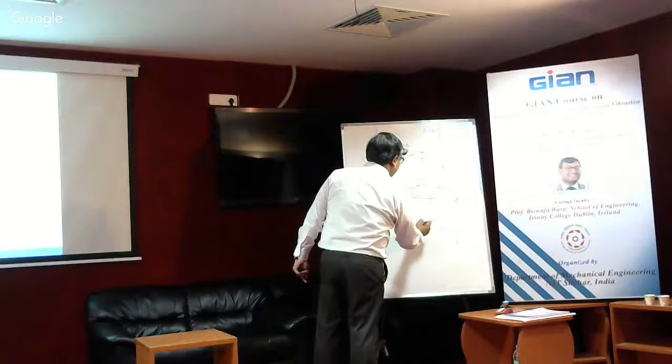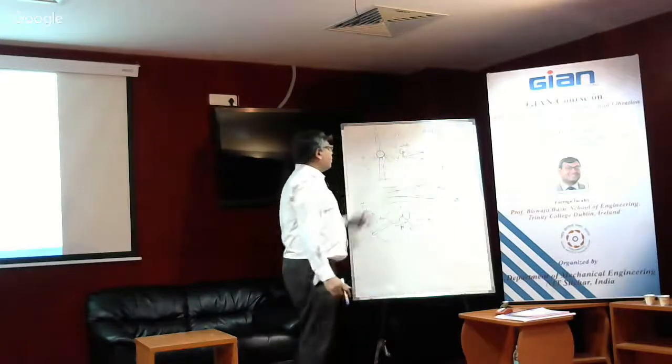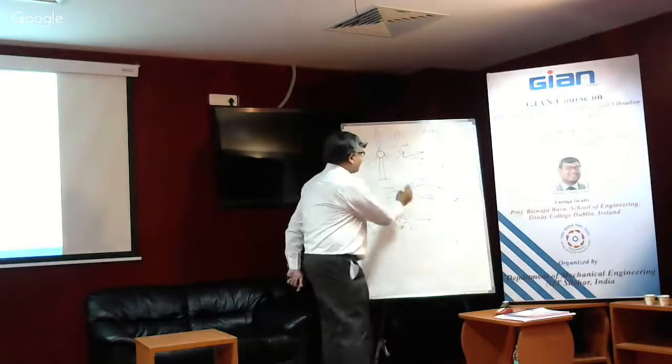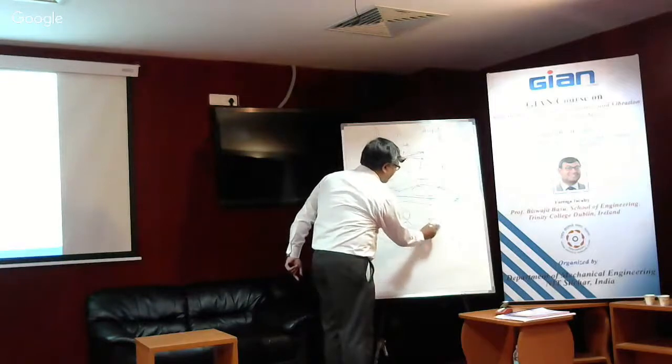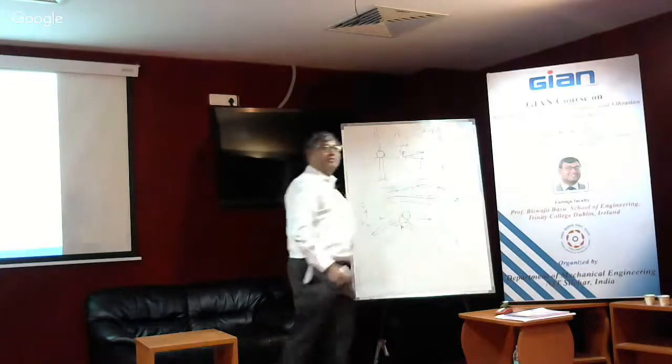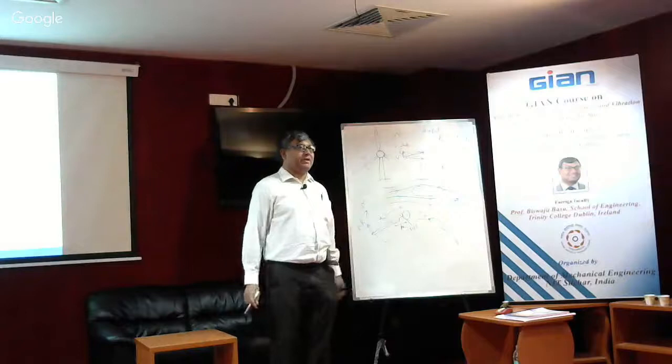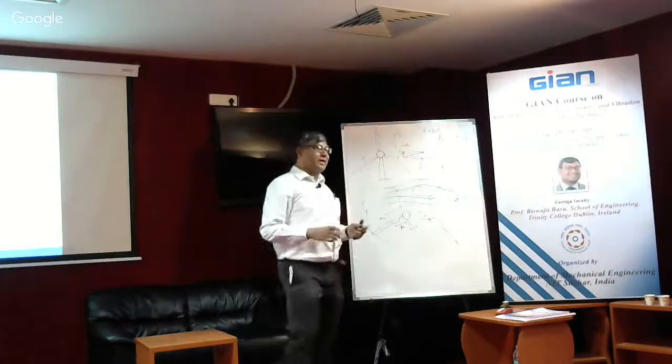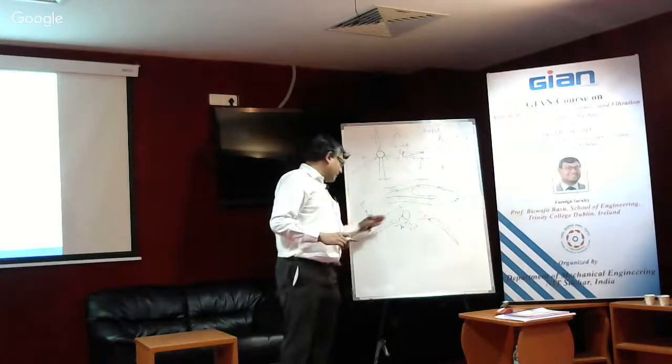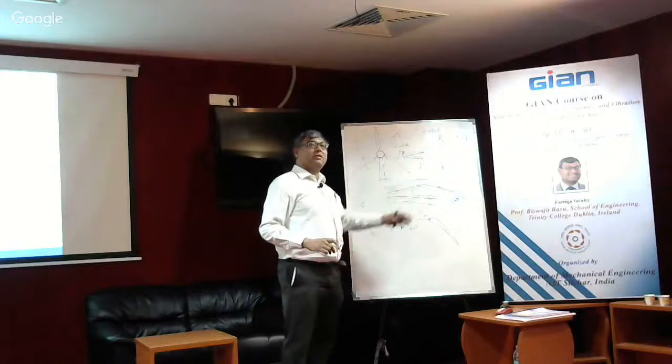So now if you have the V like this, even though there is no omega times r, the net velocity actually is still the same because the angle of attack is the same. We are twisting the blade to make sure that the angle of attack is more or less maintained along the blade.